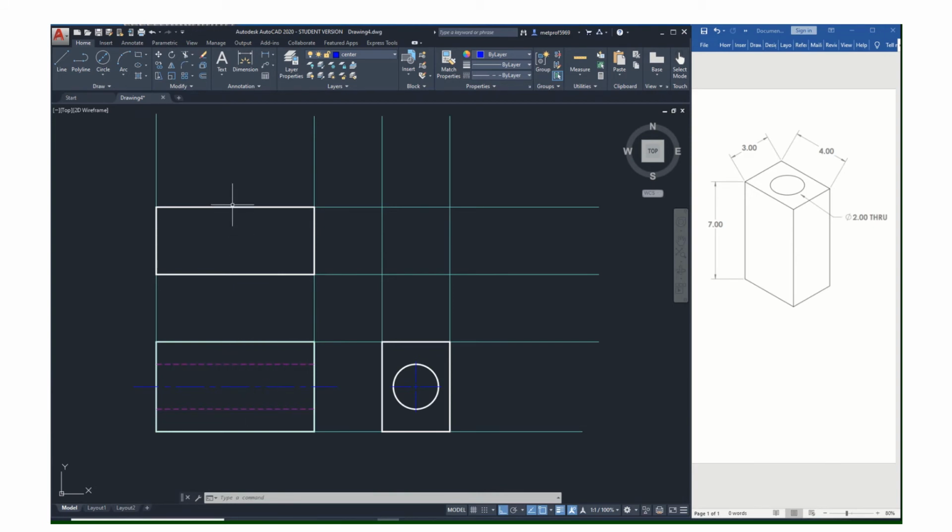So I could remeasure all that stuff, but let's use a miter line to do that. So go to my construction lines. A miter line is going to be a line that goes from that upper right-hand corner up here at a 45-degree angle. Now, because of the way I left equal space between the views, these depths of the part are the same. That creates a 45-degree angle. Otherwise, you can just draw a line using the distance tab angle command to create that.